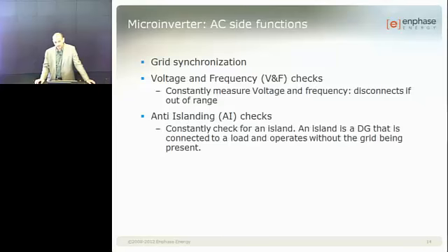If that's the case and you actually disconnect the grid, the system will keep operating forever until something changes. That's really a bad thing, because if you have somebody doing some maintenance on a system, takes the grid off, expects that everything will go off, and by really bad luck, there is a local load that matches exactly what the inverter is doing, its power is still there, and people could be killed.